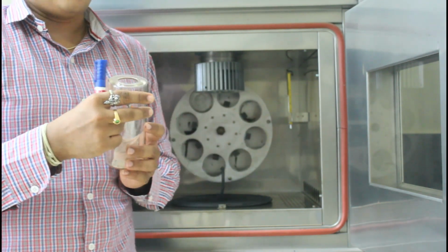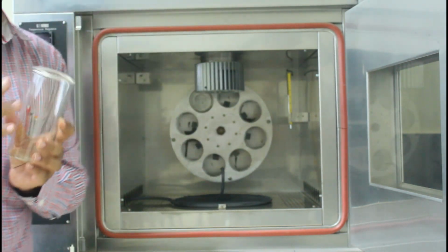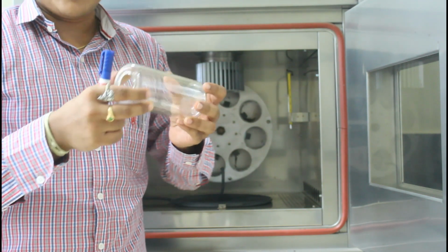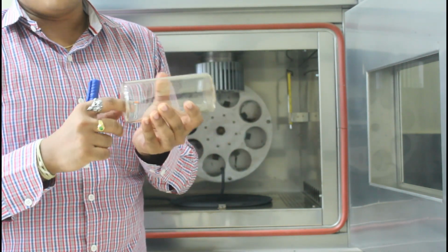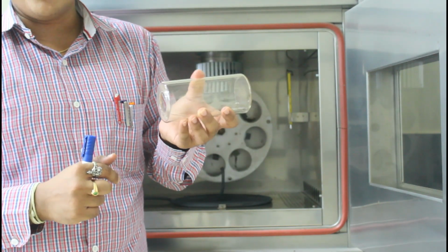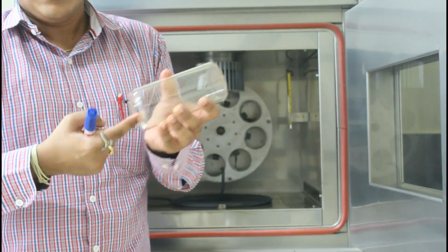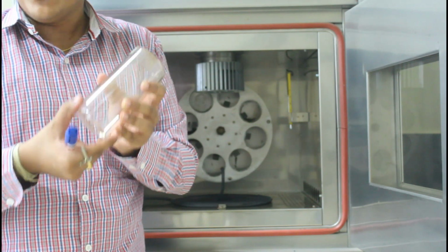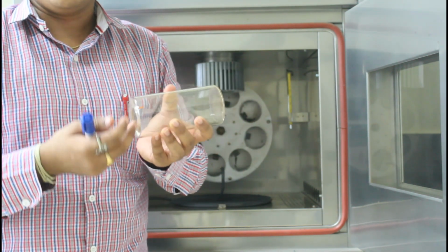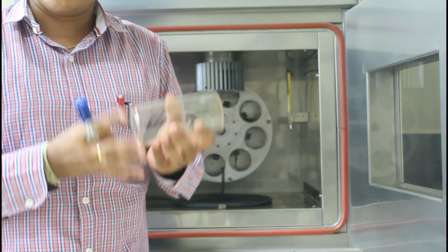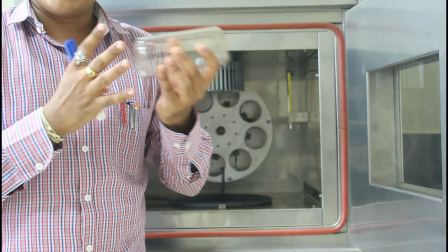But on the other hand, if you want to find some properties before and after aging, what we will do? Once we get this aged binder, we will immediately transfer it to an empty can. Right? We will use a scraper and scrape the whole bitumen and then collect it in an empty can so that we can use the aged binder for further tests like measuring complex shear modulus, measuring phase angle, measuring the viscosity.